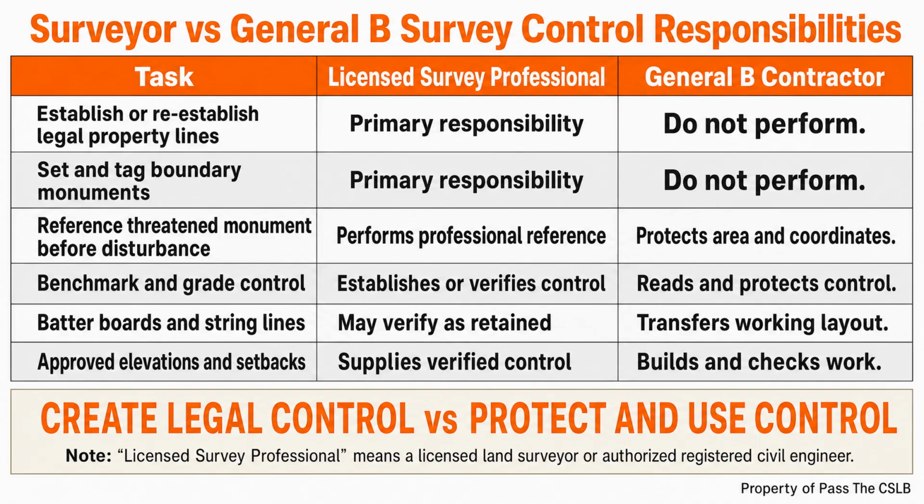A benchmark is not automatically a property corner. A fence is not automatically a property line. A wooden stake that says finished floor is not permission to move a legal monument. The contractor has to know what kind of control is present before touching it.